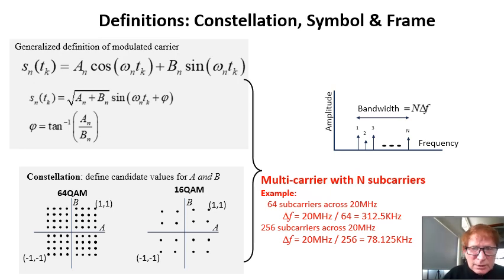At this point, we see that each A and B pair or constellation grid point can represent a new piece of information. Also, each of the 64 subcarriers can be encoded with a unique A and B pair. Use of these multiple subcarriers and the QAM modulation approach provides OFDM with a significant degree of parallelism that is one key to the achievable high data rates from OFDM.